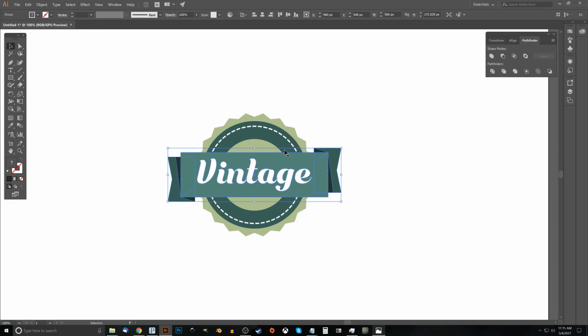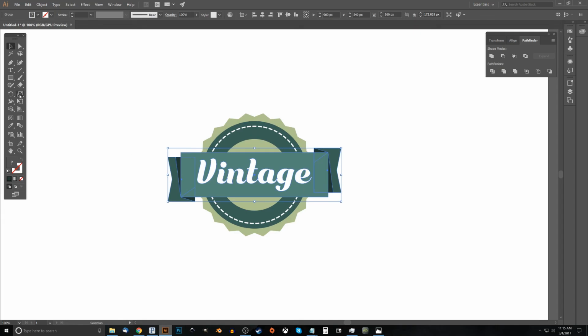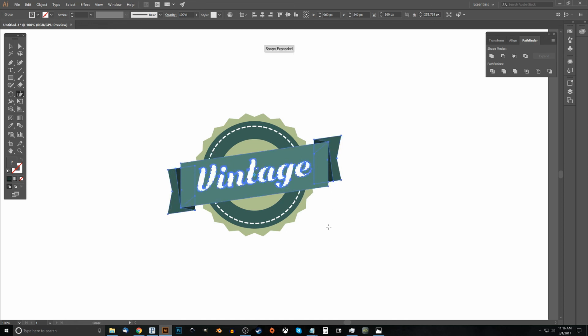So what I'm going to do now is shear this a little bit so it's running diagonally. If you notice here in the thumbnail, it's running diagonally like that. So let me go back. To do that, I'll find the scale tool, click and hold on that, and go down to the Shear tool. Then I'll click and drag this upward to shear this up a little bit. And then I'll hold Shift to lock it onto the vertical axis, and I'll shear it maybe that much. That's pretty good. We can go back to the Select tool, and click off of the graphic to deselect everything.